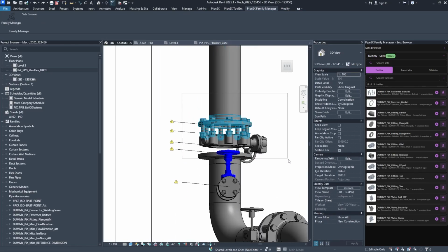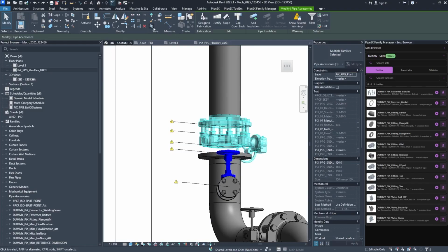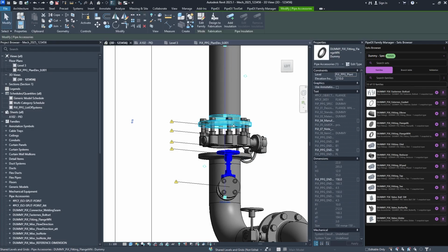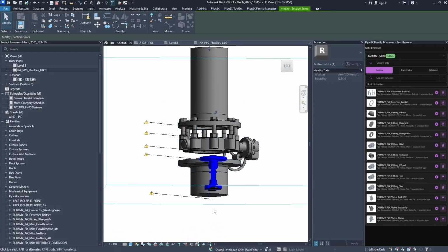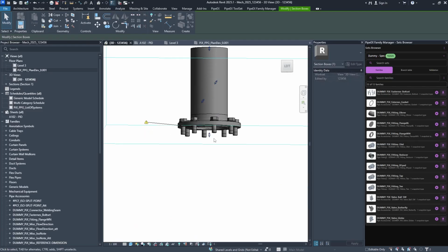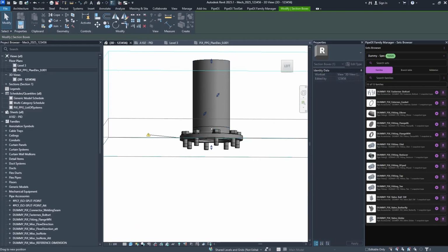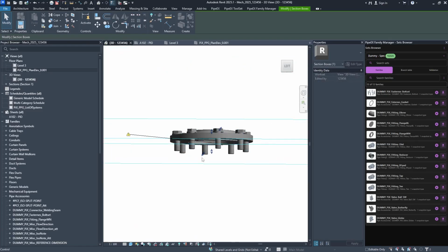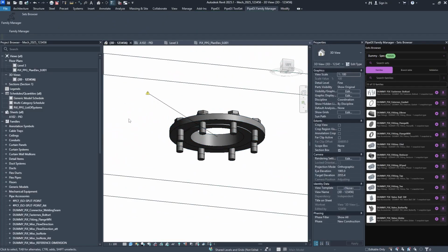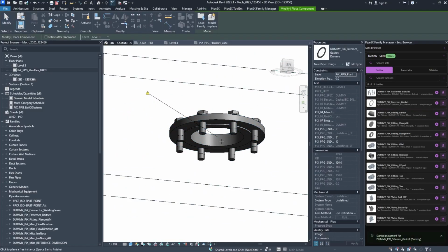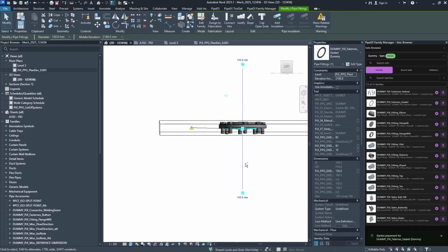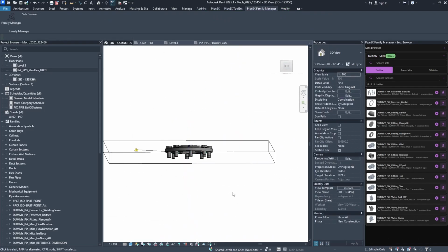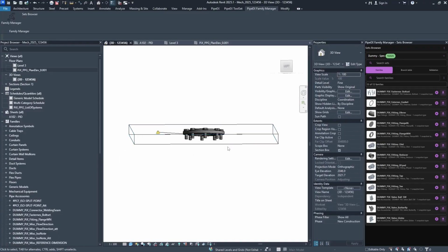Okay, to save me some time, you can also do this trick. Just limit the selection box to only flange. Then move it slightly above, so you can see only this surface. And then it will be connected to the proper spot. That's one of the tricks that I can share with you.